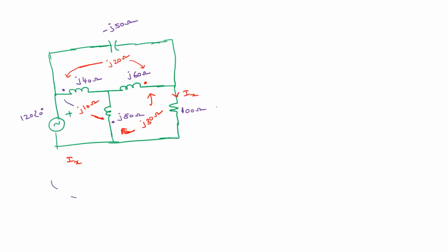It looks complex, but it is actually an easy one, right? Agree? So now let us assume this is coil 1, this is coil 2 and this is coil 3. How many mutually induced voltages will act on coil 1? Two, right? Similarly for coil 2, two, and for coil 3, two. So each one has two dependent sources in series with it. Agree? Yes, sir. No confusion, right?